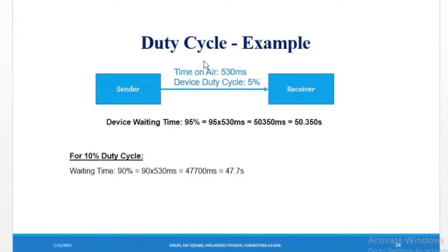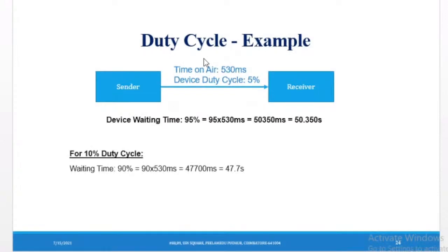We will not give any such assurance to the customer. Depending upon the customer's place only can we identify it, because RSSI and SNR will be different there. If it is a noisy or dusty environment, all of those things can affect it, because it is RF based communication.